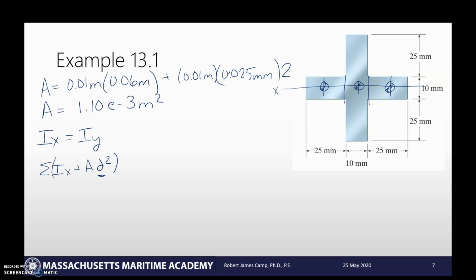What does that mean? Well, that means d is 0. And in this case, since it's symmetrical, Ix and Iy are the same. You could do the same thing and calculate the moment of inertia about the y-axis. My centroid's in the middle, and if I break it here and here, the centroids of those individual pieces are going to lie along that y-axis. So once again, there's no x deviation, so there is no d. D is going to be 0 because they lie on the same line. There's no multiplier effect for it to be farther out from the centroid of everything than the other ones.